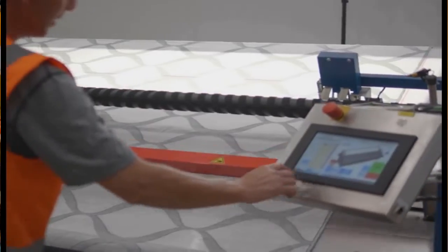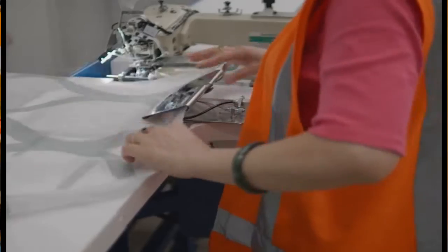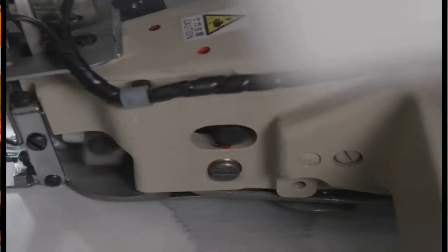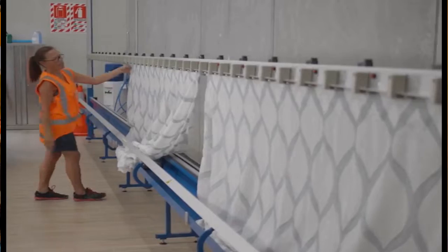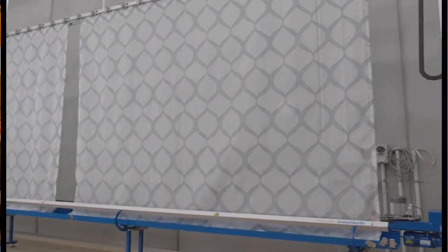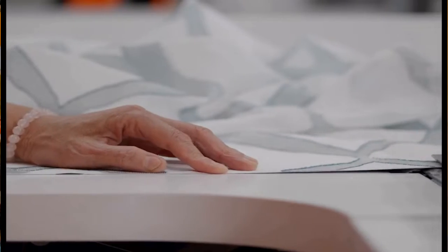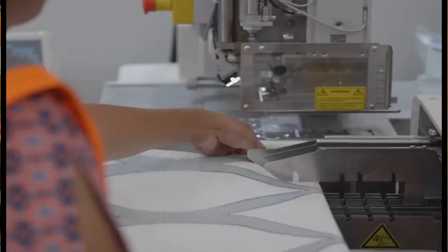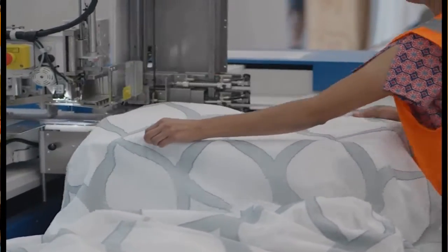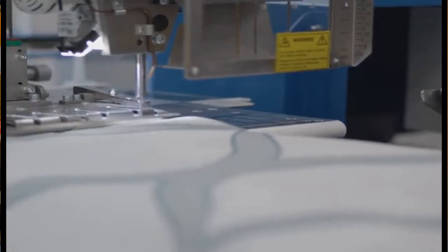Lastly, the fabric needs some manufacturing processes to become a complete curtain product. The fabric needs to be cut to size, and both the side hems and the bottom seams are blind stitched at the same time. The fabric needs to cut all the curtains at once to ensure the pattern and the texture will match perfectly. Then joining and capping, drops in motion, and finishing the corners. After that, the curtains are finished and are ready to be pressed and folded for delivery. Finally, a complete curtain is produced.